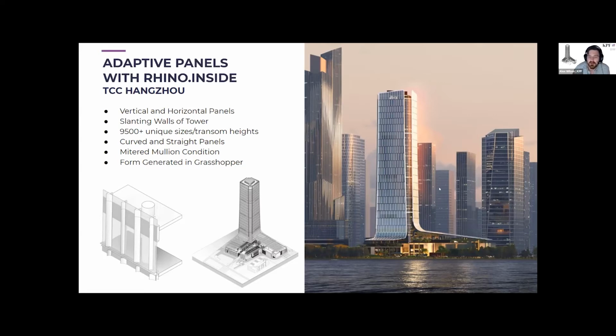Also, because of the way the facade is designed, you have vertical mullions, or slightly slanted vertical mullions technically, on the major facades. Below that, the horizontal mullions do not respect the tangent of the facade itself. The horizontal mullions respect the floor level, the vertical mullions respect the facade. So you have a difference in mullion logic built into the curtain wall panels themselves.